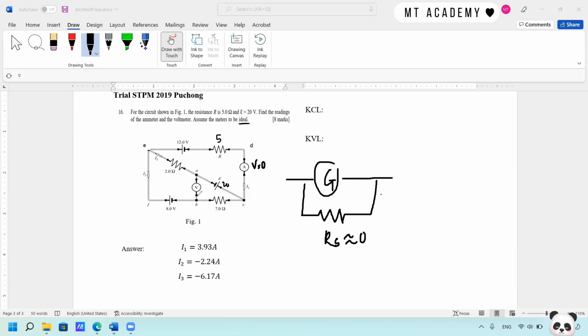Just like how we learned about the effect of the internal resistance in the battery, which can cause a voltage drop across the circuit. As for the voltmeter, it is a galvanometer connected in series with a multiplier. The multiplier should be as large as possible, approximately infinity in ideal cases. So when you have infinite resistance, there is no current flowing through the voltmeter, so it will not affect the current reading or the voltage reading in the circuit.